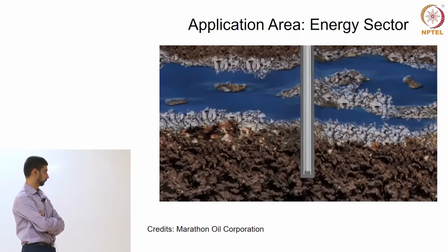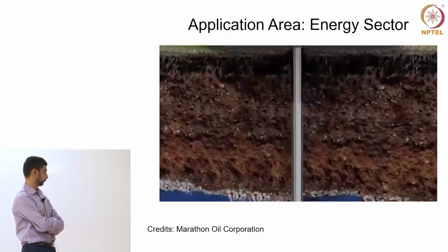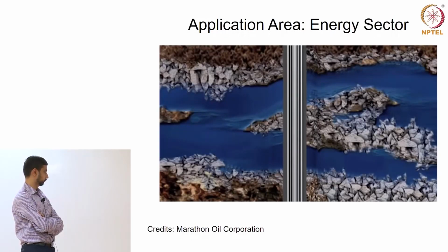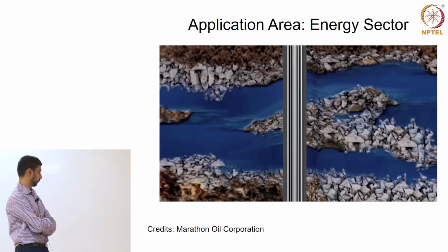When it reaches the bottom, it is pumped back up between the casing and the borehole wall, creating an impermeable additional protective barrier between the wellbore and any freshwater sources. In some cases, depending on the geology of the area and the depth of the well, additional casing sections may be run and, like surface casing, are then cemented in place to ensure no movement of fluids or gas between those layers and the groundwater sources.